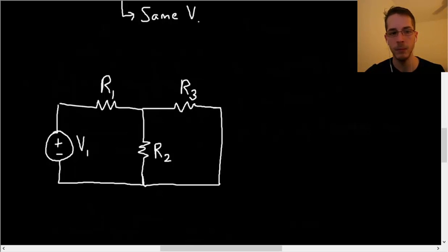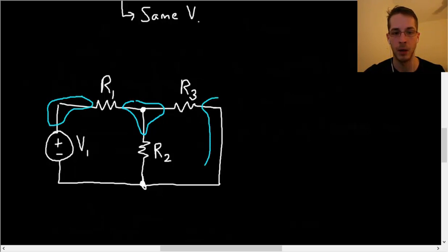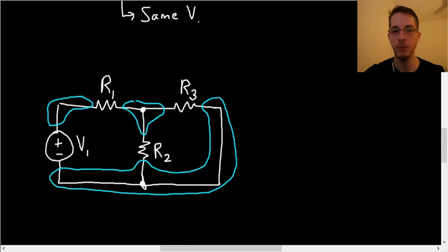So in this circuit, we're going to look at the nodes here. It's a pretty common misconception to think that the intersections of wire themselves, like these little dots, are just the nodes, and that's it. That's not correct. The actual nodes here are entire sections of wire. So here in this circuit, we're going to have 3 nodes.